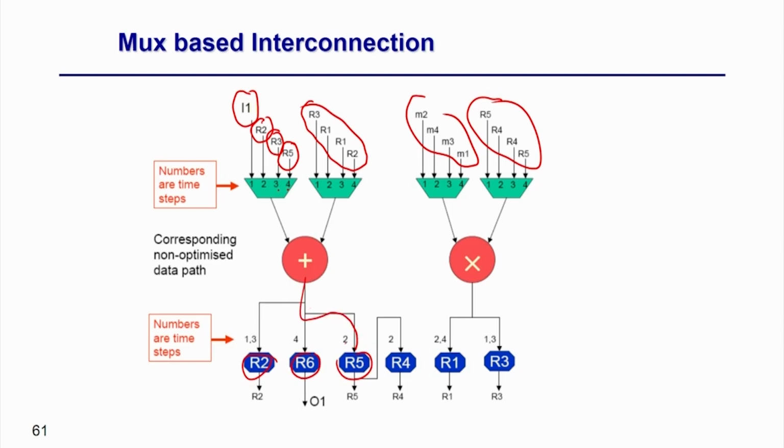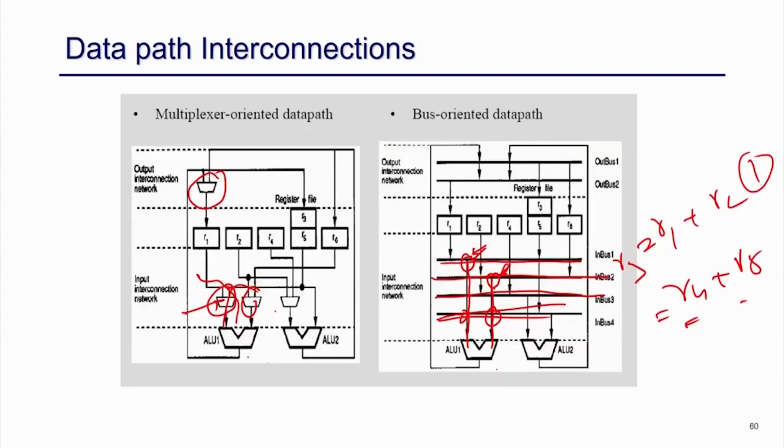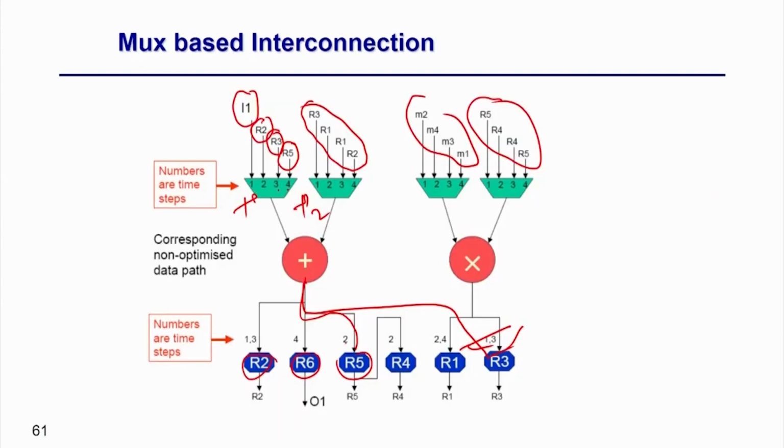So, conventionally what we are going to do is put a 4:1 mux here, where the control signal length will be 2, here also a 4:1 mux with a 2 bit control signal, and so on. So, this is the data path I am going to generate blindly if I generate the data path. Similarly here, since there are two outputs which are all connected, there is no problem, but if there are multiple, for example the adder output also coming here, then I have to put a mux here. So, this is what I have generated here, and this is something known.